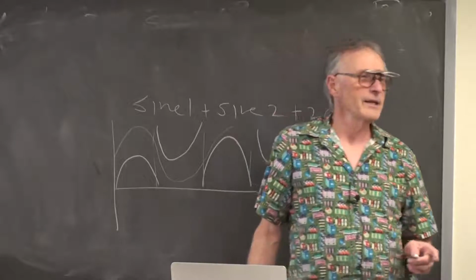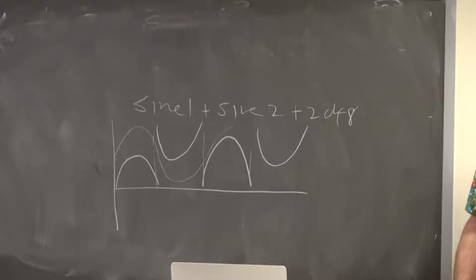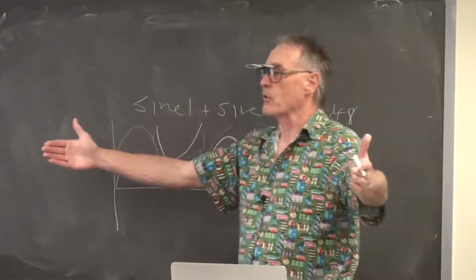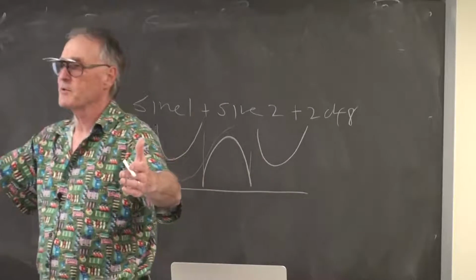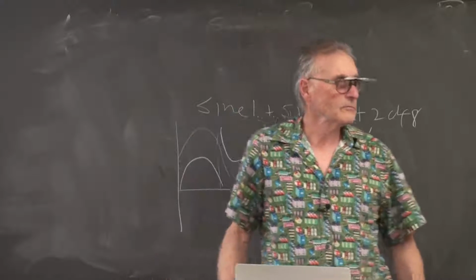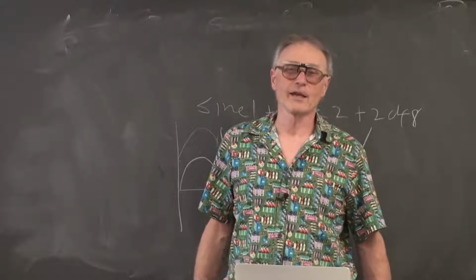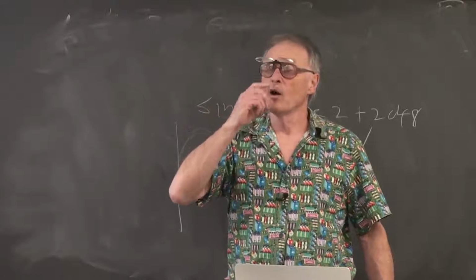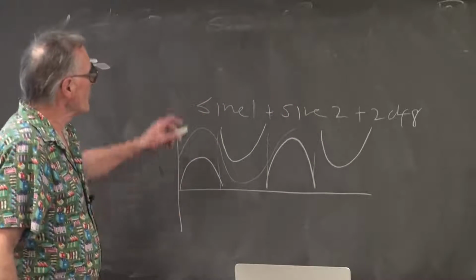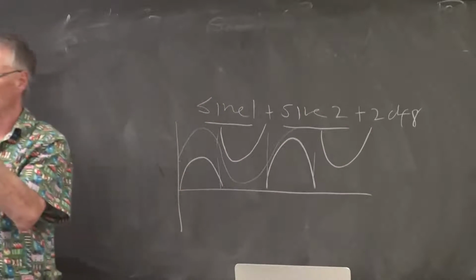And when you play that, it sounds nasty. Why does it sound nasty? Because every sharp transition generates a broad spectral component in Fourier space, which comes across as a crackle or a hiss or growl. It'll sound broadband. That's all I can say. You get so you can recognize the sound of overflow distortion. Sad but true. So you have to scale these tables so that the sum never overflows.